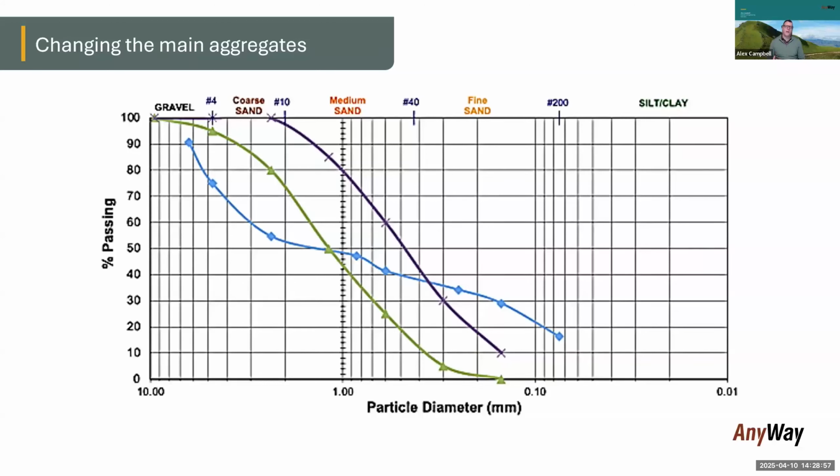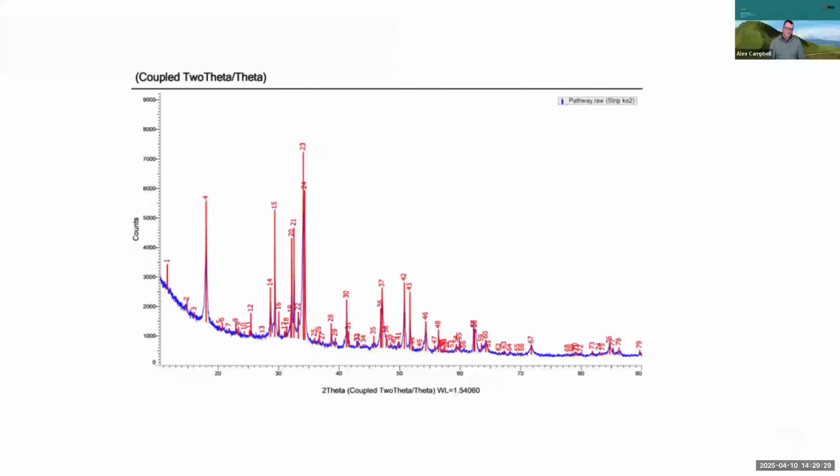It has a much lower large particle size fraction and a much larger small particle size fraction. And it's that smaller particle size fraction that typically gives issues related to shrinkage cracking. You want that larger particle fraction to give it substance and load-bearing properties. So it was a very challenging material to work with, but one that we needed to find a solution for.